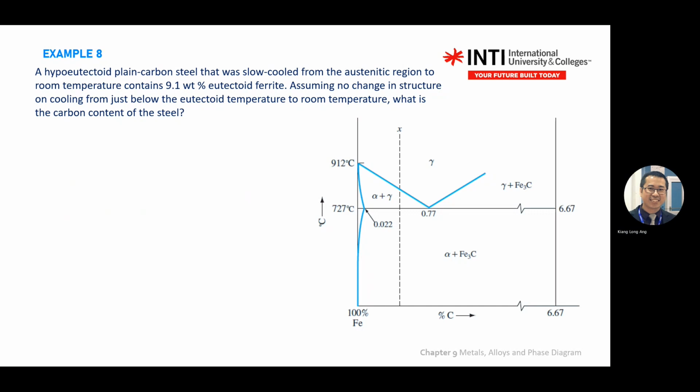How do you guess alpha? When gamma drops, you get alpha plus gamma, so you start to see alpha already. Then you drop further, and in this region you get alpha, ferrum, carbon. So it must change to something that exists between these two. It won't have gamma here because it has already changed from FCC to BCC. So here you only have alpha.